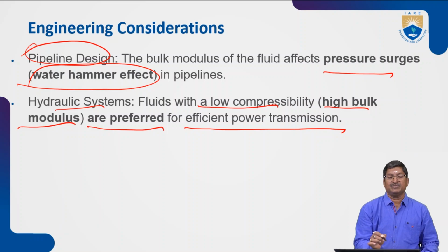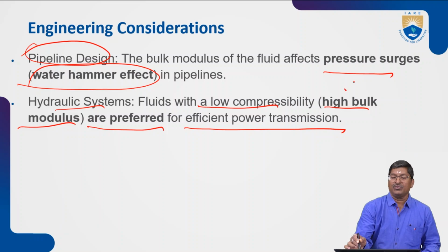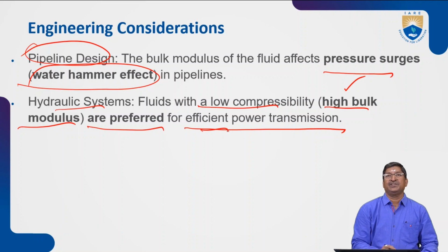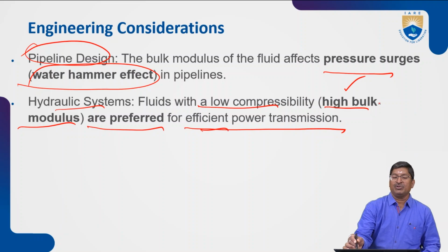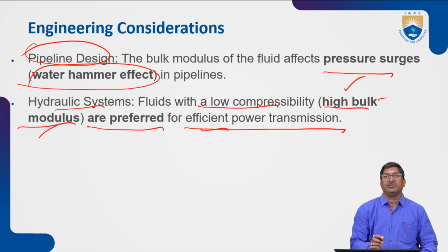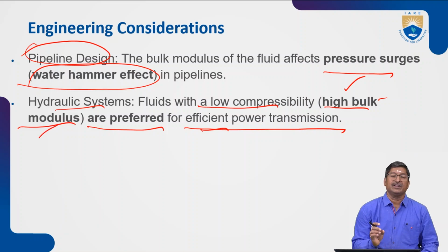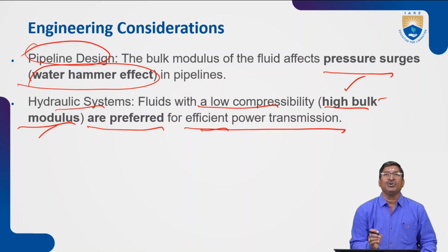And in hydraulic systems, if you want the best efficient power transmission, then you have to use high bulk modulus liquids. If you utilize high bulk modulus liquids, then the power transmission will be more efficient.